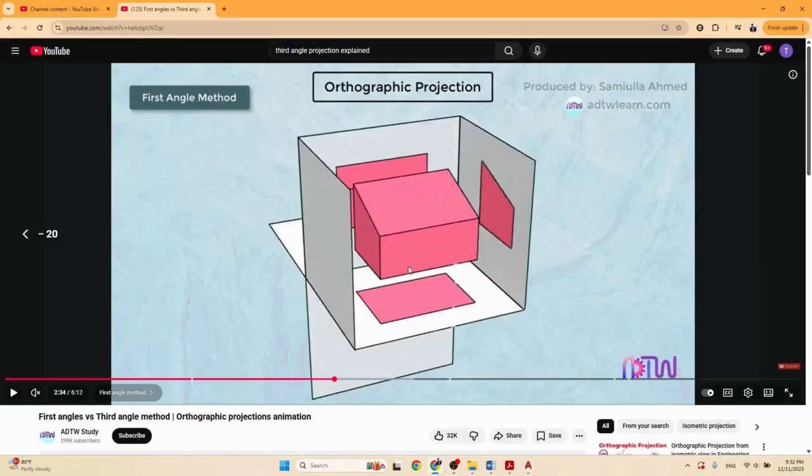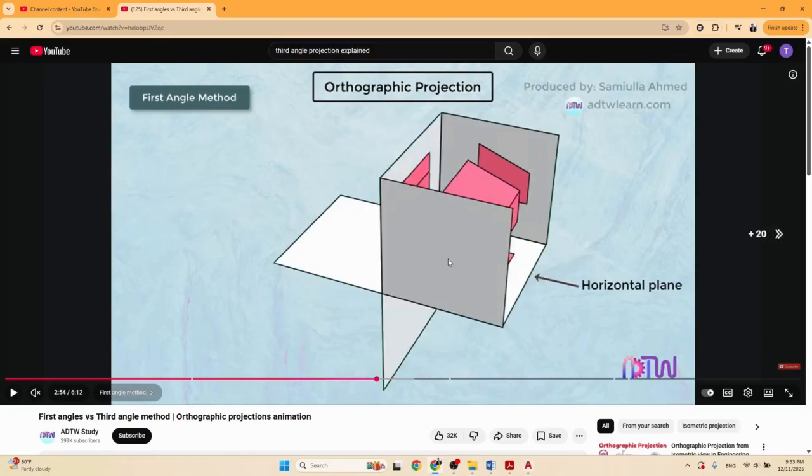Remember, this is the left side, it is placed on the right. And this side over here, if you're looking from this direction, is going to be projected onto this auxiliary plane. I like to think of it as saying in first angle projection, all of the views are reversed.